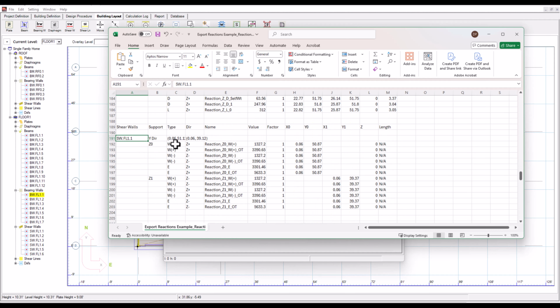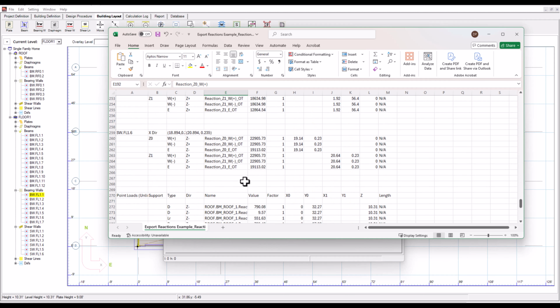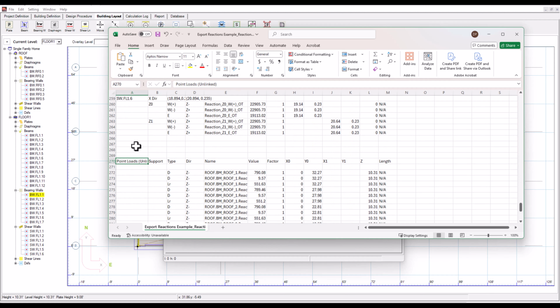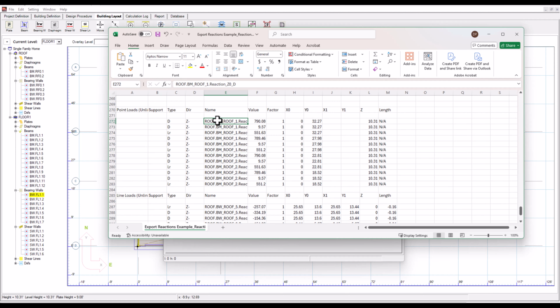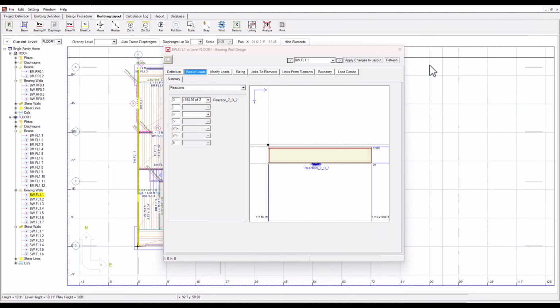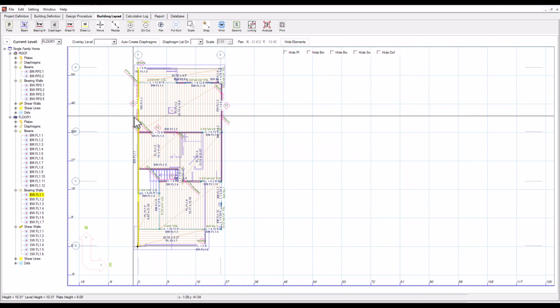And then the last piece is going to be the shear walls. In shear walls you get reactions for the posts and the wind and the earthquake as well. Here you can see their locations of where these loads came from. So you have all of that in shear walls, and then lastly, if you have any loads that didn't come across from the level above, it is tracked for you. So these loads here are going to be something I want to trace down the building and either line up with loads carrying them below, or I can account for them separately. So that gives you all the information you need for your base reactions, and you can take that into another program.